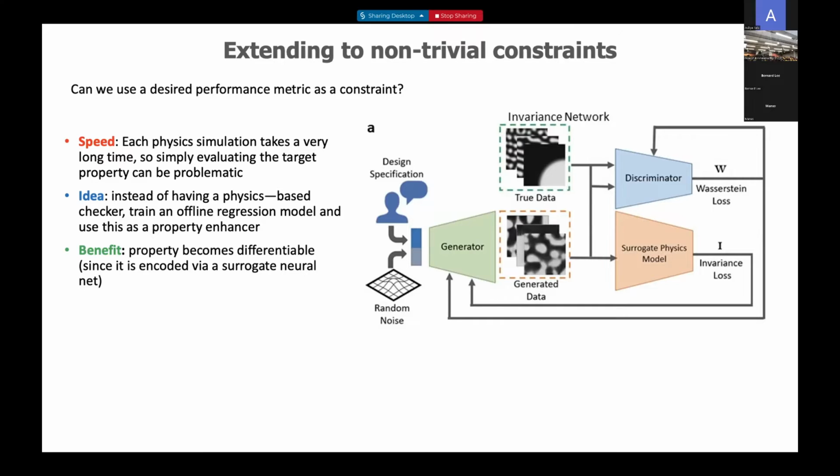If I know certain chemistry properties of my molecules, let's say this is my mobility, this is my Young's modulus. Given this information, this is where the design specifications come in, and then I'm going to design a microstructure that's aware of that. So if I have a low mobility metal, it's going to create microstructures with smaller grains, and for a high mobility metal it has to create a different microstructure.